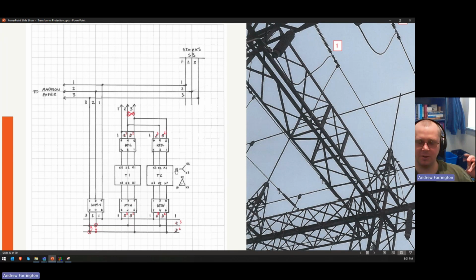So it turns out the phase shift for this transformer didn't match the phase shift for the local utility. This really emphasizes a point I was trying to make, that you've got to be paying attention to this, not only at the local substation, because these two transformers paralleled just fine because they had the same phase shift, but they couldn't parallel to this other transformer that was remote to this facility and actually only was tied in some of the time for an emergency backup situation.